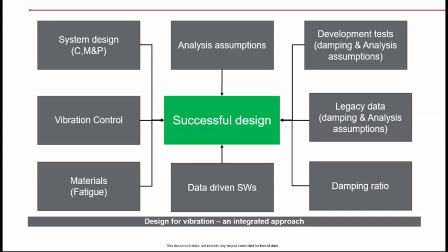But if the excitation level is a customer requirement or it's coming from a certain source which you have to honor, then you cannot do anything at the test stage. You have to come back, understand the system design again, and incorporate damping methods, additive damping treatments, or change your design itself to meet that, if it is so high during the test. Does that answer your question, Sridhar?